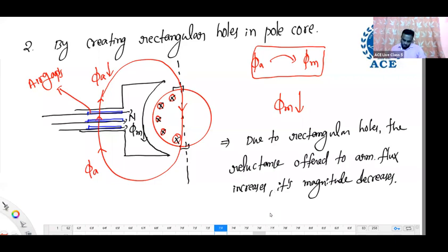By increasing the main field strength, armature reaction increases equally as the EMF and the induced current magnitude increase. Because here, observe, when increasing the strength of the main flux, we don't increase it by so much. We will increase a little. Why? Because there is some demagnetizing effect. Whatever demagnetizing is taking place, that we will compensate. Like that, a little strength of main flux we increase, but not so much. Okay.